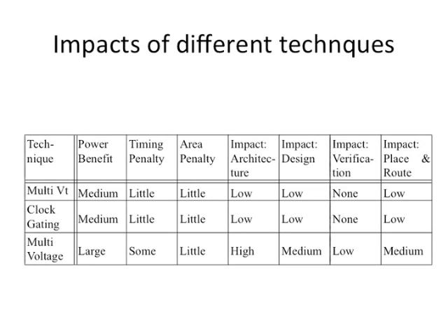You could also have standard cell gates where you have a mix of threshold voltages in the same gate. Some transistors are low threshold, some are high threshold and so on. So those are more complicated gates, but you can make those also. Once the gate is made, it's very easily usable by the design tools for synthesis.